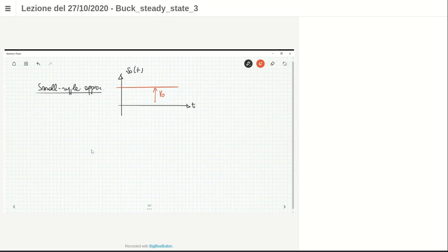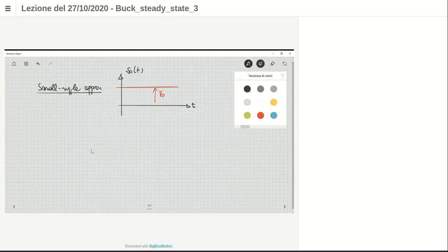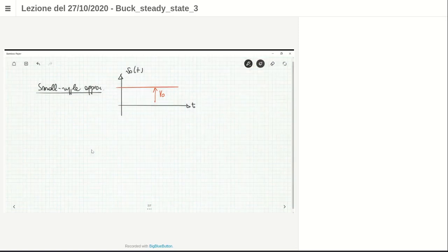This never happens, as I already said at the beginning of this lecture, because the filtering action of the inductance and the C0 capacitance is not perfect. Always you have at the output some residual components at high frequency, the switching frequency, and all the harmonics. So typically you have to consider this ripple in your design, to the point that as a specification you always have that delta V naught is less than some maximum value.